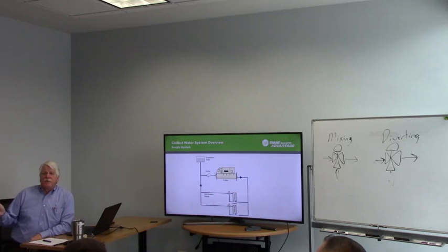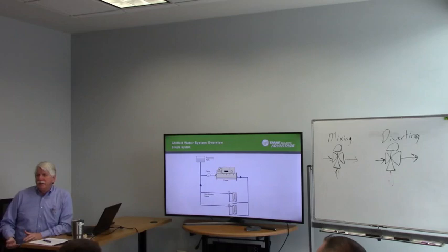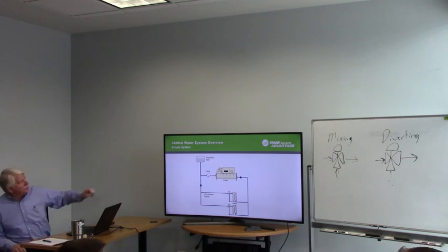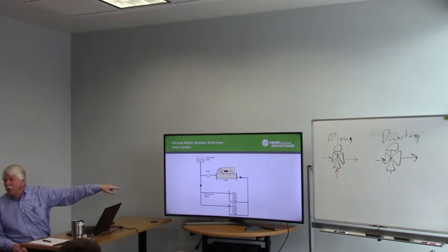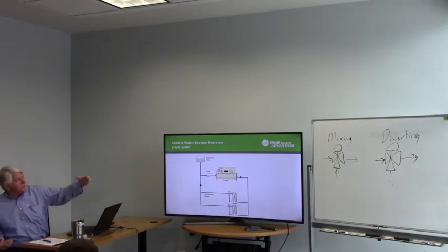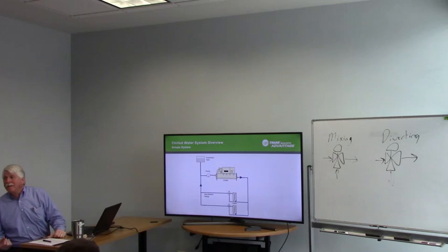All system design changes that have happened in the last 40 years have all happened for energy reasons, okay? We're trying to make systems more efficient. And the first thing you see is we're pumping a lot of water all the time, whether we need it or not. The same reason that we have VAV air systems is the same reason that we have variable flow pumping systems. It's not because they're intrinsically better, it's because we can save energy in operating them.